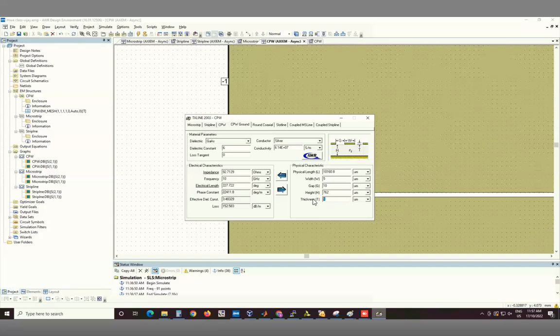So, okay, this is a practical issue. The dielectric material, the substrate I have been using so far for modeling is a circuit board which we use for making typically bigger size structures. It has 762 micron thickness and there's 35 micron thick copper because we typically make structures very big.